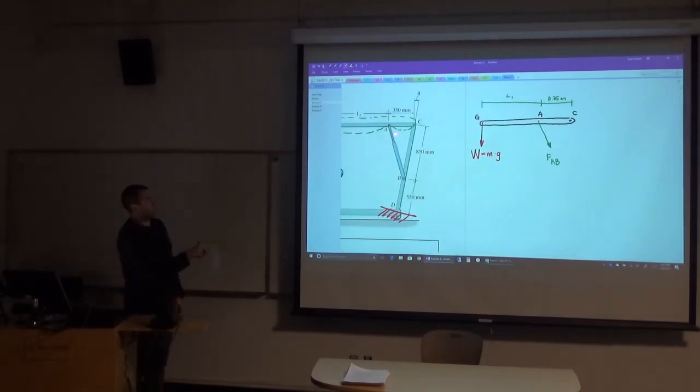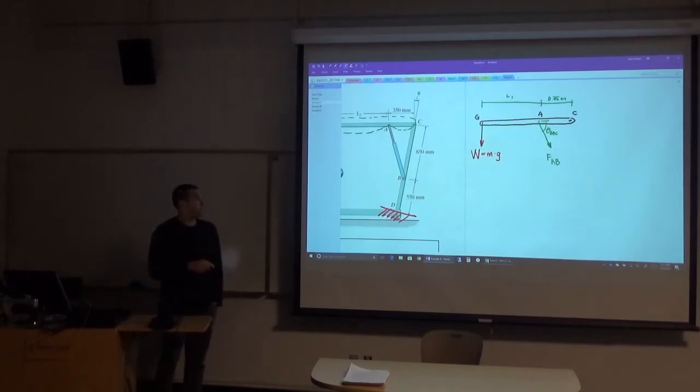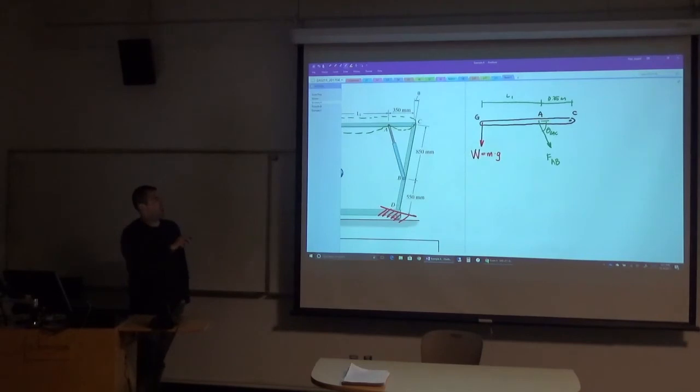And then we need to do a little bit of trig, maybe like law of sines or law of cosines, to figure out this angle right here. I'll just call this theta BAC. Again, there's always a possibility of a law of sines type problem here. I know the length of this side, I know the length of this side, and based off this angle theta, I could calculate at least one of the angles. And so you can figure out the angle here of this vertex at A using either law of sines or law of cosines. So you have enough geometric information to figure out this angle right here, and so the orientation is a known value.